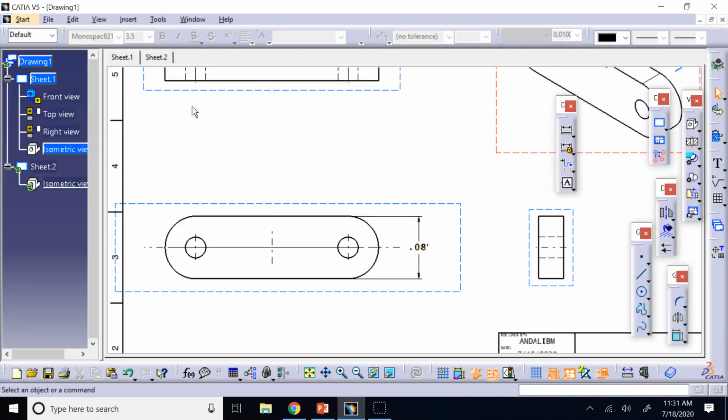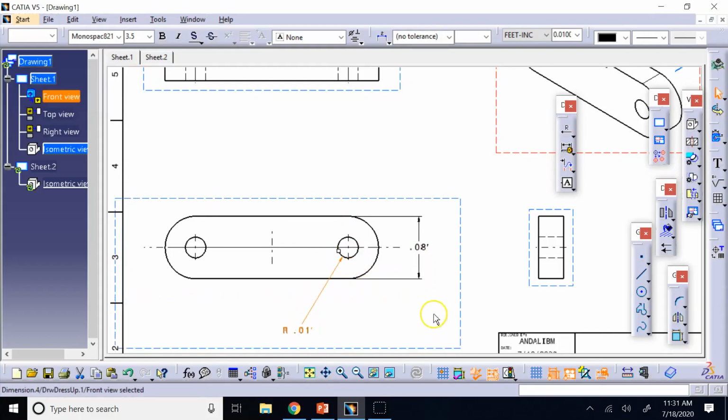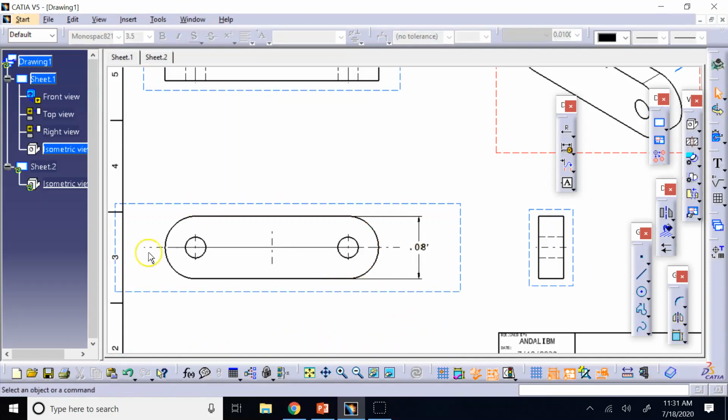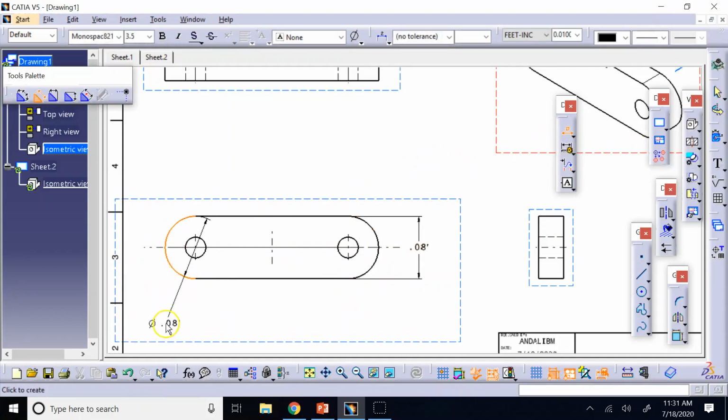I've seen this a ton. My students use this guy, they use radius for it. They come and apply a radius to this full circle. This is wrong. This is a full circle, you never do radius. Or for this arc here, or this arc, semicircle, they use diameter. They say, hey, I want the diameter of this. Don't do that. These are wrong.